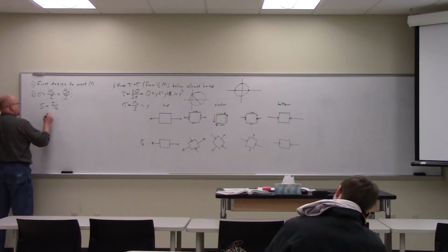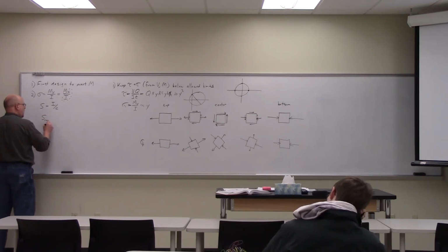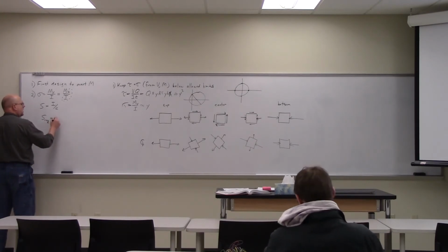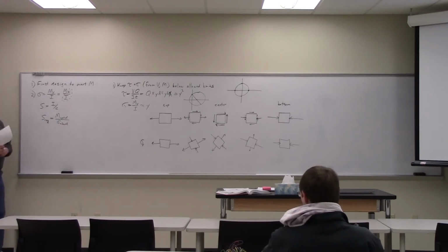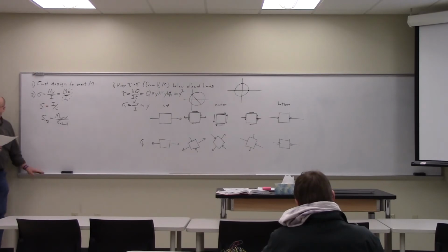So the required section modulus is going to be the ratio of the applied moment to the allowed stress. So for every beam geometry, we can define a section modulus.